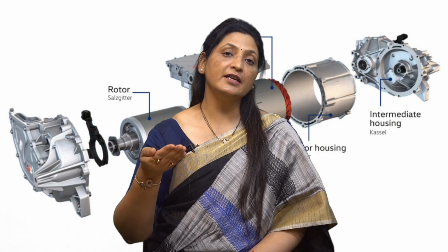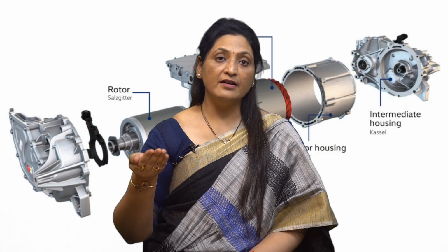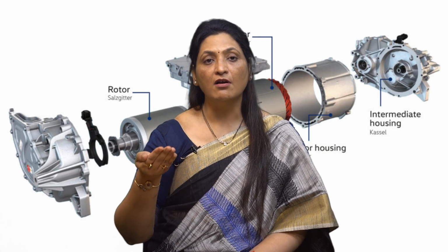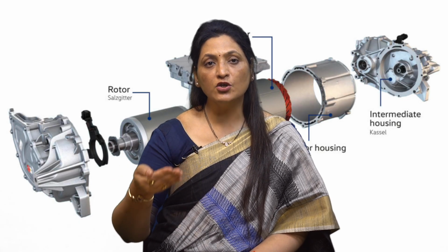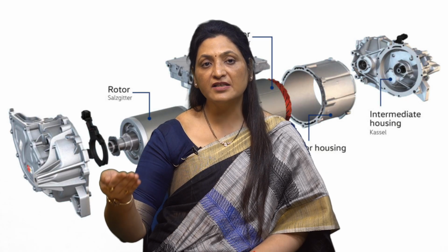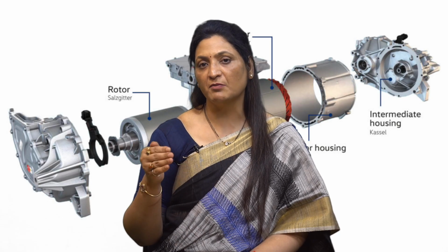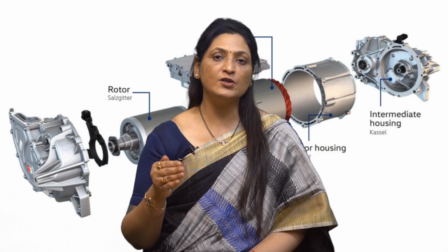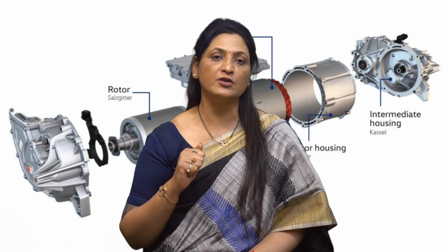Duty cycle is also very important to be considered, and it is a measure used to describe the operating pattern of a machine or device over a period of time. The duty cycle, or the ratio of the time the motor spends running to the total time, affects the choice of power rating. Say if a motor runs for 1 minute and rests for 3 minutes, the duty cycle would be 25%, meaning the motor is operating 25% of the time and resting 75% of the time.